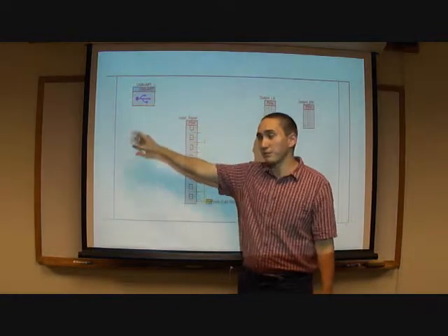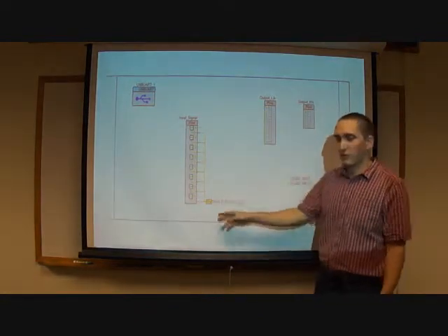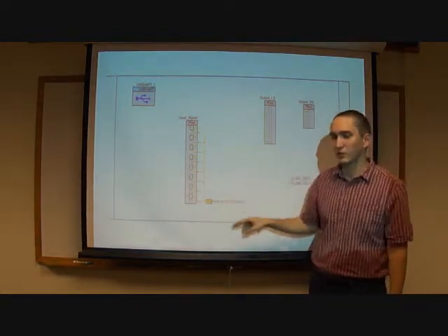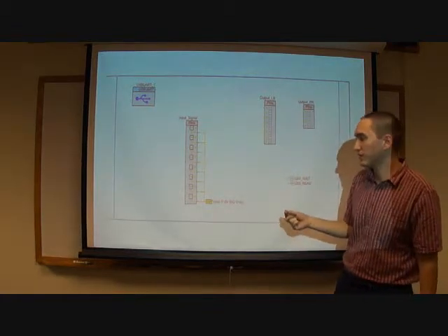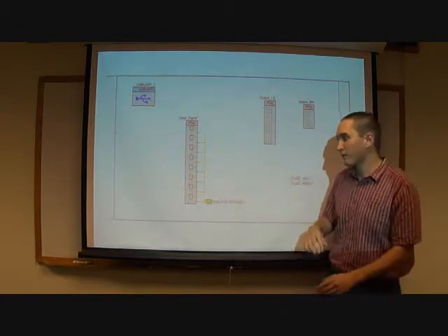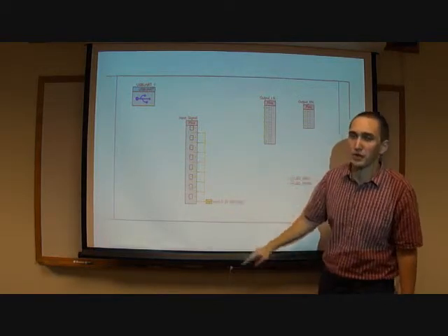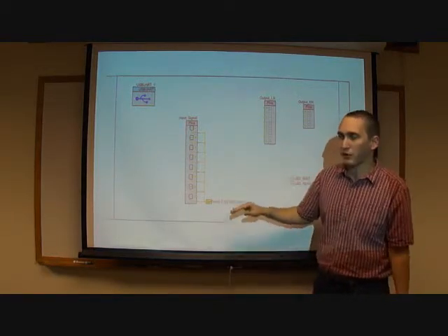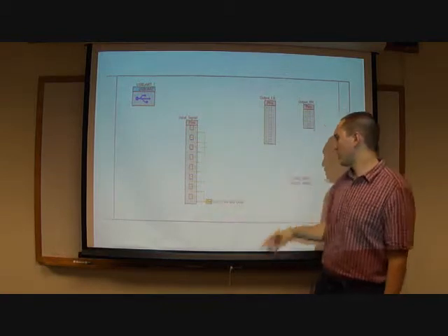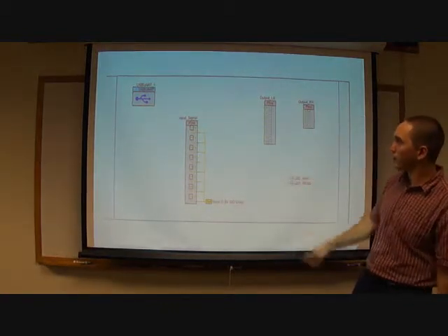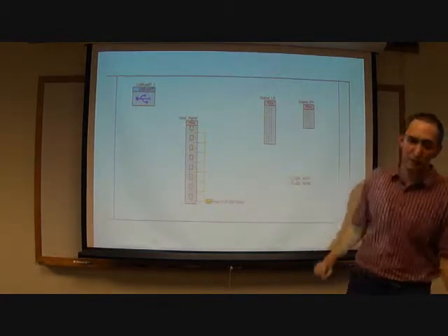The real money part of this is the input signals, which are mapped to special input-output pins, and they let you reference inputs at a bunch of different voltages. That's how we're going to be able to get our 1.8 volt, our 3.3 volt, and our 5 volt. And over here we have our LED control output, our output level select, and our output enable.